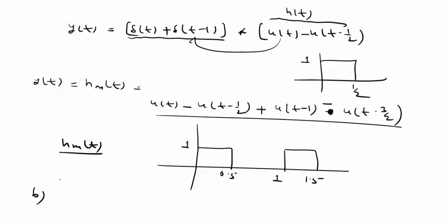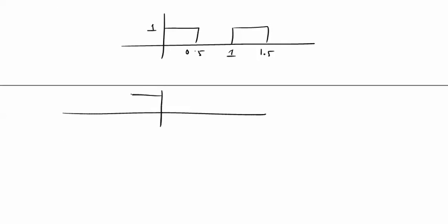Question b asks us to find the pulse s(t) which is matched with this filter. We want to calculate the match filter of this pattern given to us, with amplitudes 1.5, 1 and 1.5. To calculate the match filter of this, just take the negative of this pattern. By negation we get this result.